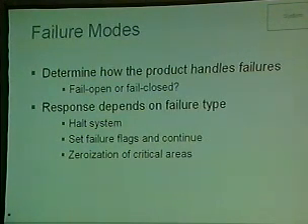Will your system fail open, fail closed? Will it fail in a way that the ciphertext is mangled somewhat? There were some papers released about vulnerabilities and key leaking through Chinese remainder theorem based attacks on hardware failures. You really need to determine what the response merits depending on the failure detected.